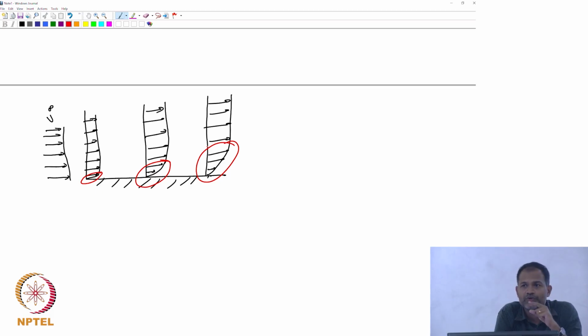So this is where we are going to define our boundary layer thickness: the region which is affected by the solid plate. Now, in principle, all the fluid up to infinity will also see it. The fluid layer gets slowed down and it really reaches far.